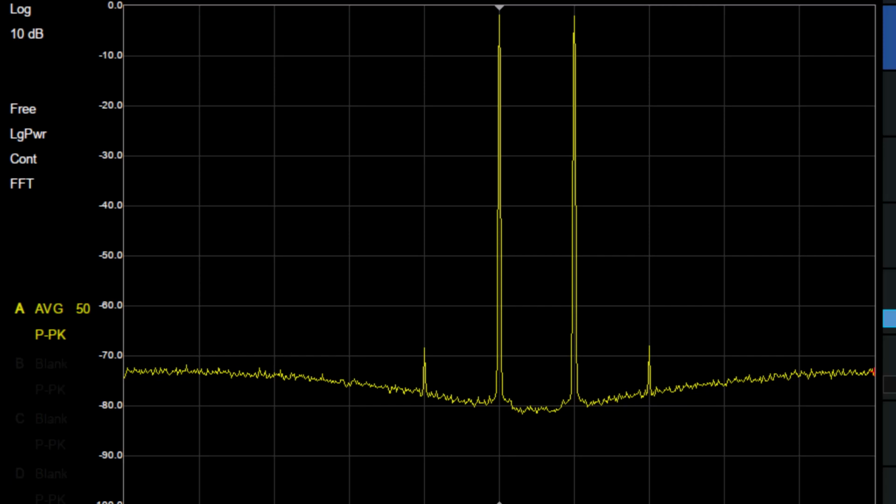Now, if the transmitter has problems, if it's not exactly linear, you can get some harmonics generated, so you have multiple tones, multiple frequencies. The tones are produced with equal power levels, so that the only variable is the different tone or the frequencies. Now the output can be examined using an oscilloscope to see what other signals are on the output, and if you see other frequencies or other tones, you know that the linearity is not perfect in the transmitter. So that's really what you're trying to test, is linearity.